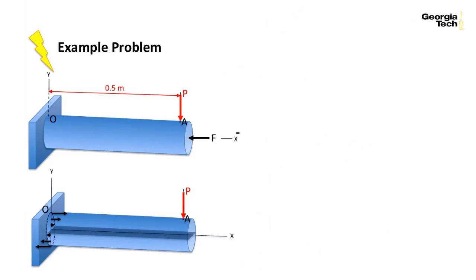So now what we've determined is, and here's a shortcut, because this beam isn't constrained anywhere between the point that you want the stress and the point where the load is being applied, you can do a simpler bending moment where you just say M is equal to force times distance, which is equal to, in this case, 500 newtons times 0.5 meters, or 250 Newton meters, and it's a negative bending moment.